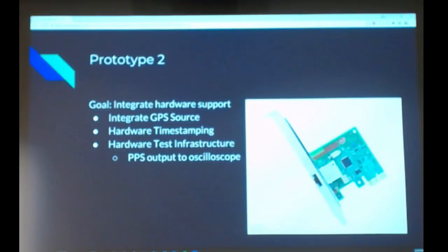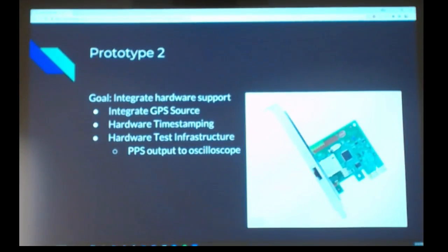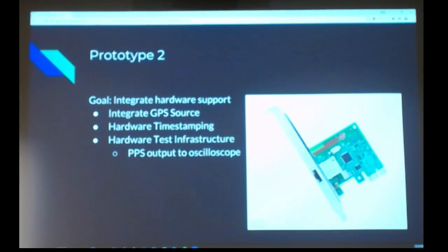We also wanted to get the most accurate results from our system, so we utilized the pulse per second output on the network cards along with the pulse per second output on the T-Sync GPS card to determine the offset between the devices utilizing an oscilloscope.